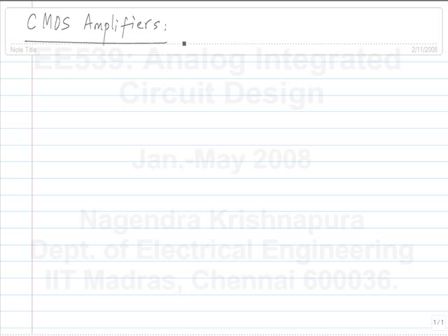The output power can never be larger than the input power, because such a thing would be a generator. Now, we do not have any power generators on our devices, right. So, it can only consume power, it will dissipate power, but if you have a nonlinear device and if you arrange it in the right kind of environment, I mean the right kind of biasing, then you get a small increment in the input power and a larger increment in the output power.